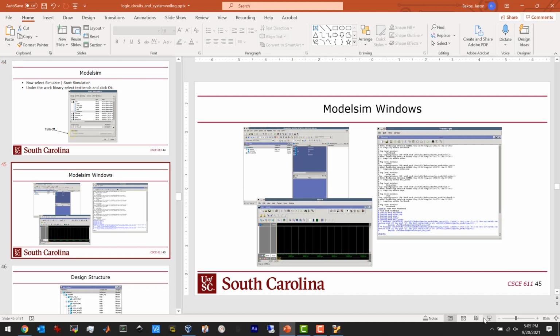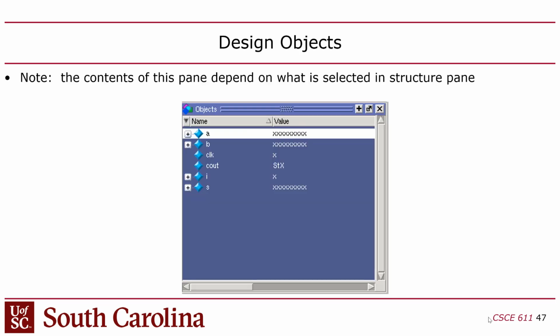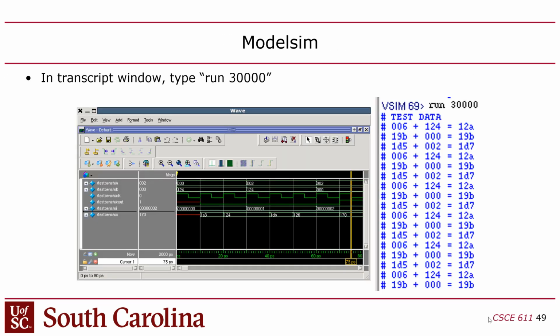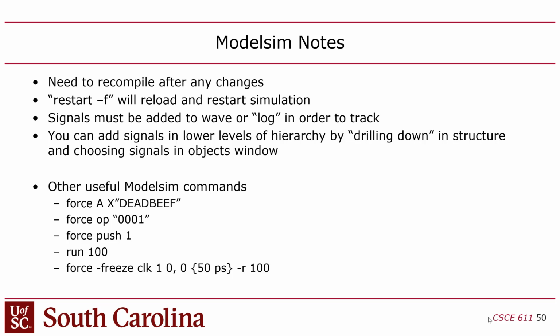Let's see, the Modelsim windows, I went over that. Design structure, yeah, I think I covered all that. Okay, in this slide, I have a few commands for Modelsim. So I showed you the force command. Now, normally, when you test, you're not going to be using force commands. We're going to use a test bench, which I'll explain in the next lecture. A test bench is when you write another Verilog module that'll actually take care of setting the inputs, right? And then also ideally checking the outputs as well. You guys with me? So you'll have another Verilog module that will be driving the input values. But if you want to do a quick and dirty simulation like I did, you can use these force commands, right?